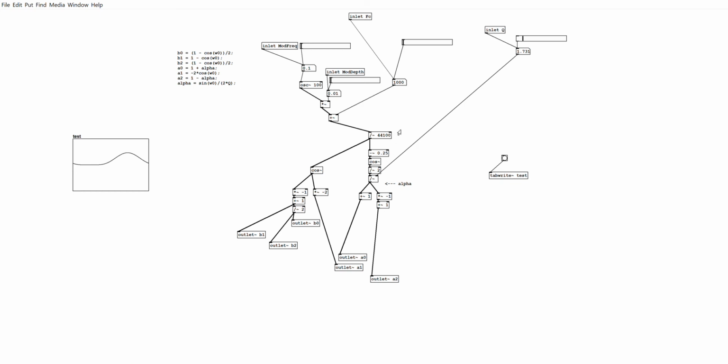And that's why we have FC divided by 44,100 minus 0.25, and then going into the inlet of the cosine block. That'll essentially yield sine of omega naught as opposed to cosine of omega naught. And then we'll divide by 2 and divide by q, which is the same as dividing by the quantity 2 times q.